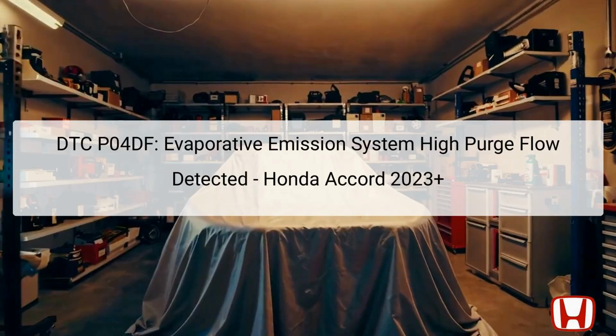The DTC P04DF indicates that the Evaporative Emission (EVAP) system is experiencing a high purge flow condition. This error occurs when the Engine Control Module (ECM), often referred to as the Powertrain Control Module (PCM), detects an abnormality in the FTP, fuel tank pressure sensor signals. The FTP sensor monitors the pressure in the fuel tank and is crucial for ensuring that the EVAP system operates efficiently by preventing fuel vapors from escaping into the atmosphere.